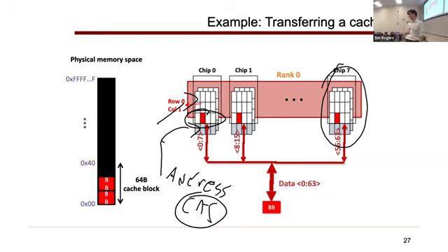So you can pipeline those. This is a simplistic diagram where it's assuming that as soon as you do the CAS, in that same cycle, the bit is going to come out on the pins. That may not be true. It may be a cycle later, which means pipelining. Again, that's dependent on the design of the memory chip, but it's possible. Other questions?